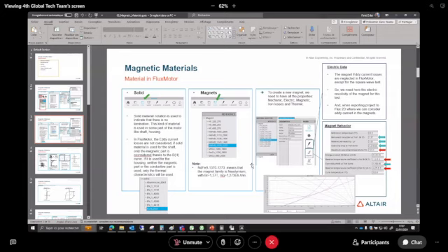Okay, then in addition to the lamination, you have a solid part, mainly for the housing and the shaft. Once again, we are not taking into account the eddy current inside the rotor. But if there is a massive part, you need to create a material corresponding to this massive part in order to use it in your computation. Because on one hand, there are no iron losses on it, only eddy current losses and hysteresis losses as well, but that model will not be applied.